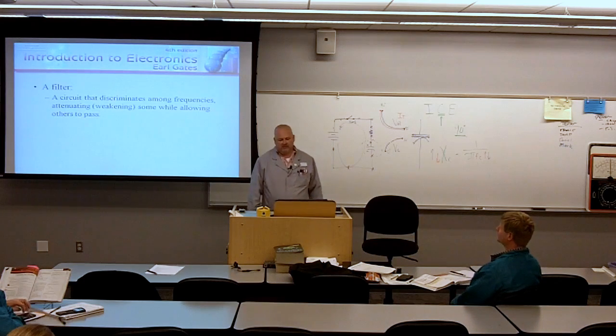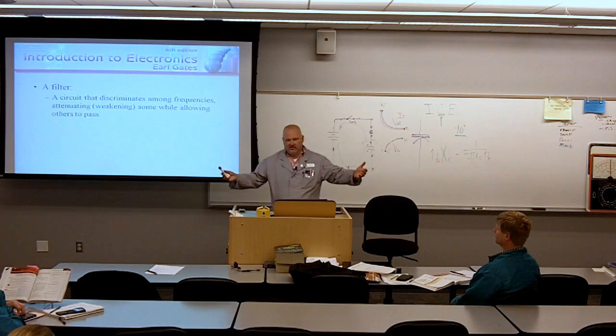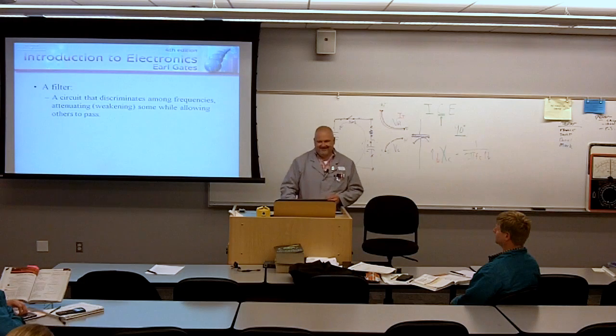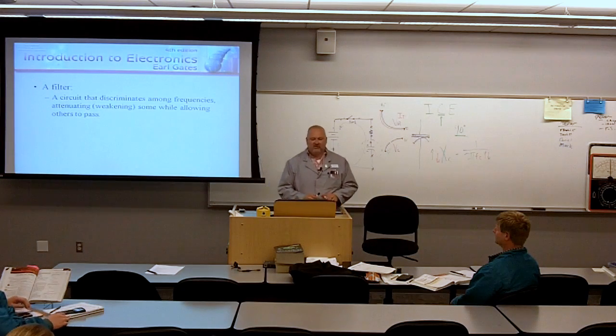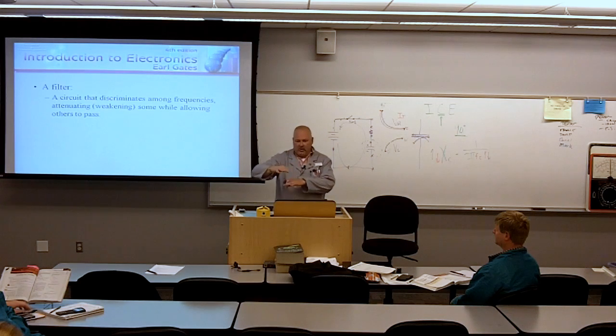A filter, this is a good one, you can go home tonight. What did you learn over at that technical college tonight? We spoke of discrimination. Because that's what we're talking about here. A filter is a circuit that discriminates among frequencies. Your $1 million word for tonight is attenuating, which is the opposite of amplifying. You've all heard of amplifying before. An amplifier, you put in a small signal, you get out a big signal. Sometimes we want to attenuate a signal. Put in a big, get out a small signal.